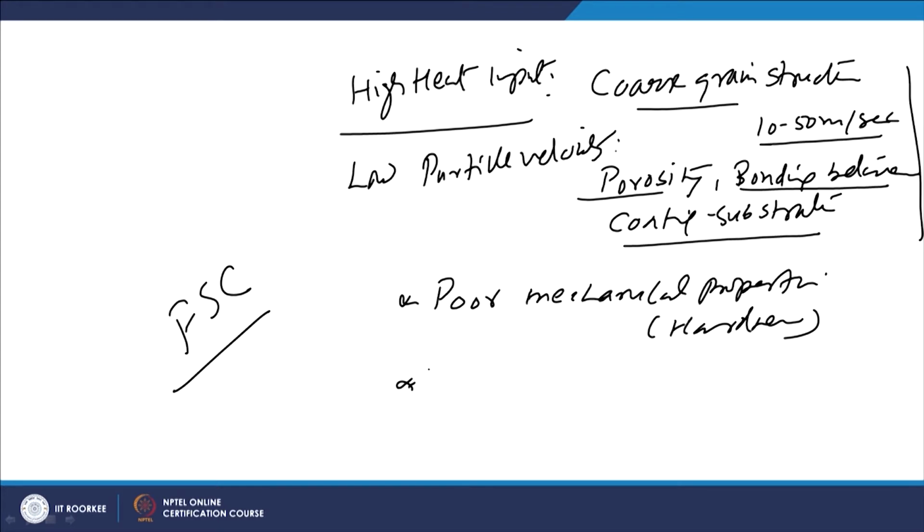And because of the poor mechanical properties, especially the hardness, we find lower wear resistance. Although it may be better than the substrate, as compared to the other processes the wear resistance offered by flame spray coatings is lower. If the same material is coated using other processes, then that may offer much better wear resistance. So, the lower wear resistance.